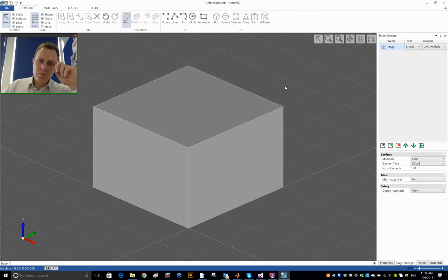Then I want to of course define the foundation on top of the box, and I'm going to model 1/4 of the problem. So I'm going to put the foundation at this point. So 3/4 of the foundation will not be modeled. Only this 1/4 that rests on the domain in here will be modeled.